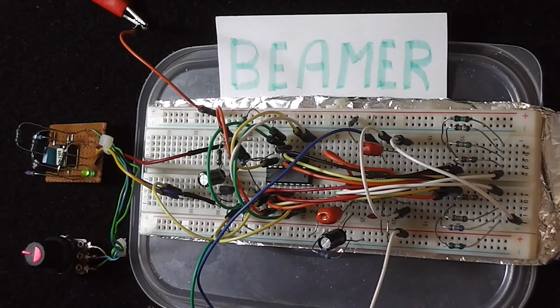I'll just go through the circuit here from left to right. First of all, we have this small board here, and on the board you have the CMOS 555. There is a PNP transistor which is providing a constant current source for the ramp generation of the 555. This has two advantages.